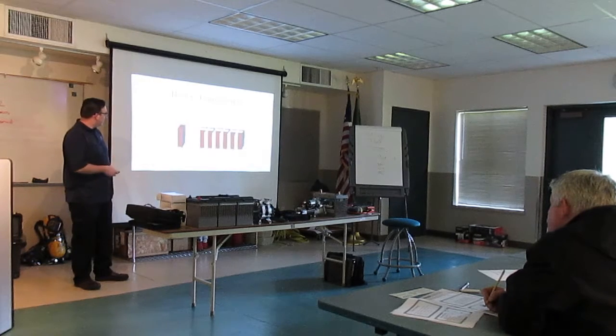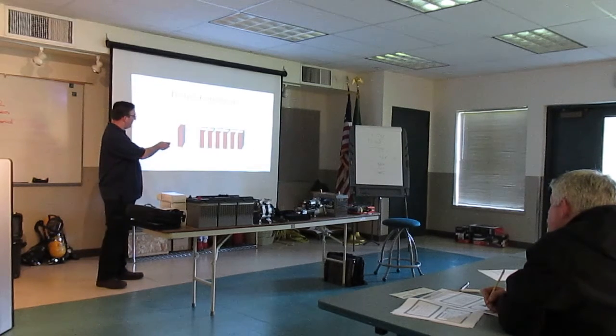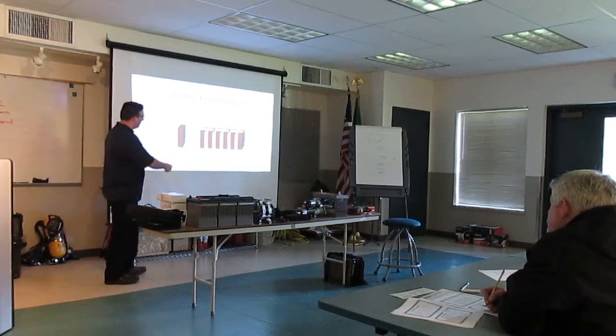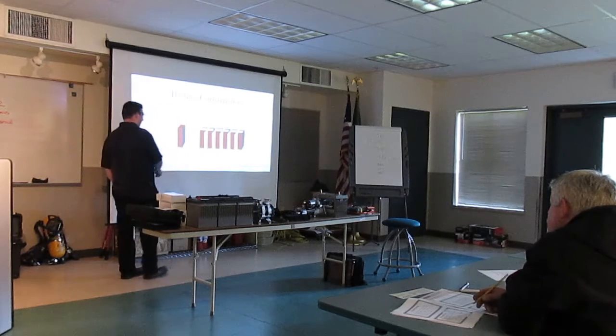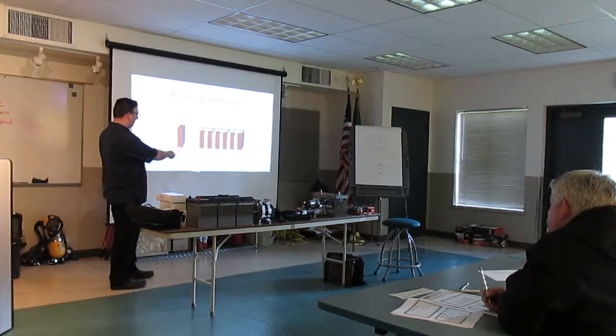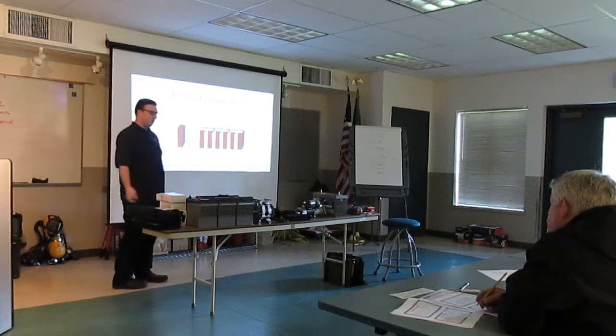Our battery construction, right? 2.1 volts each cell. We've got our 6 cells. You can see our positive to negative going across. This is one line as we're going. We have our mold there. We have our sediment chamber at the bottom, which keeps the plates from shorting out on each other.